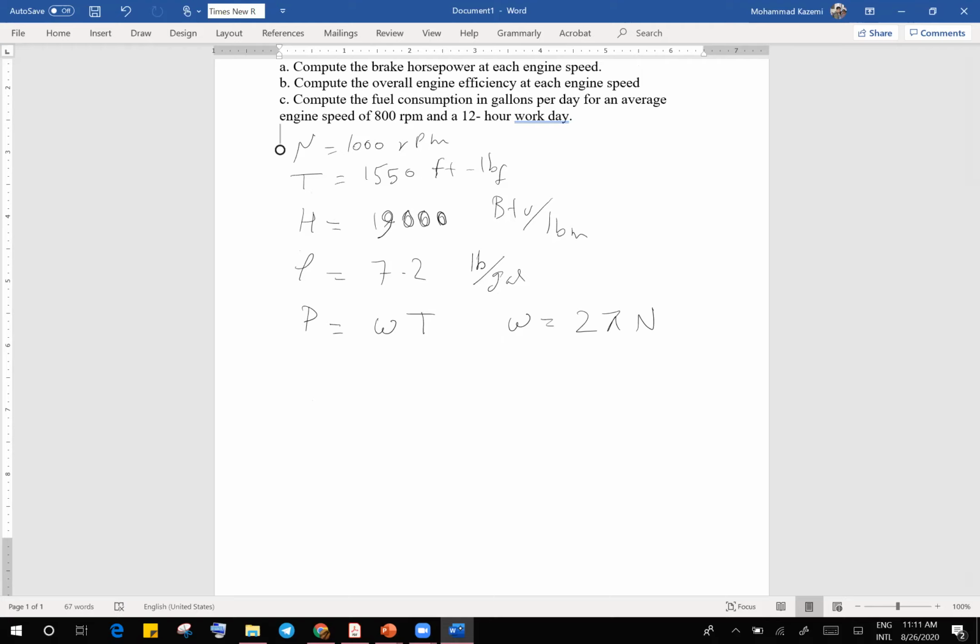So now the engine speed was that, right? The torque, we have that one. So omega is equal to 2 pi multiplied by n, which is in this case 1000, right? So pi here is 3.14 multiplied by 2 multiplied by 1000, right? So you will get 6,283.2 radian per minute. Be careful about the units, okay? What units you're putting. So this is RPM, revolution per minute, right?